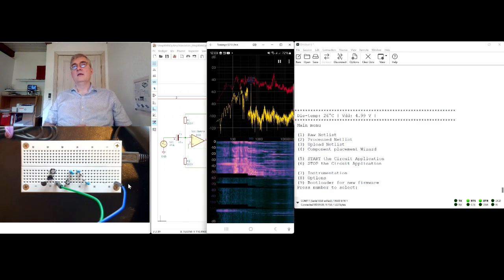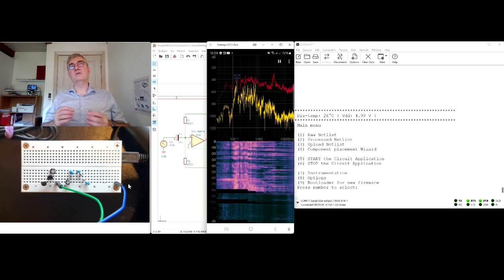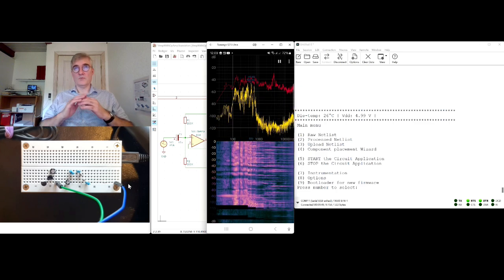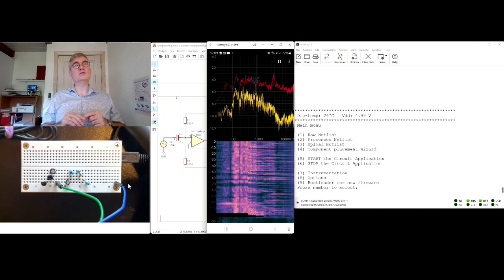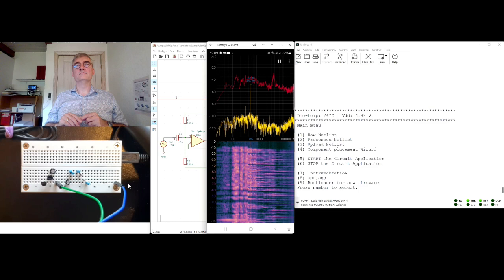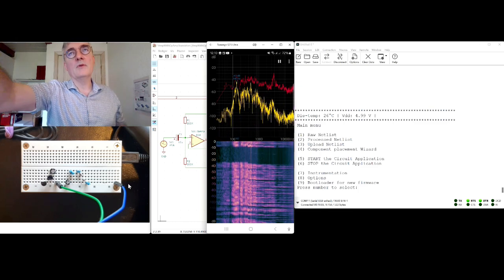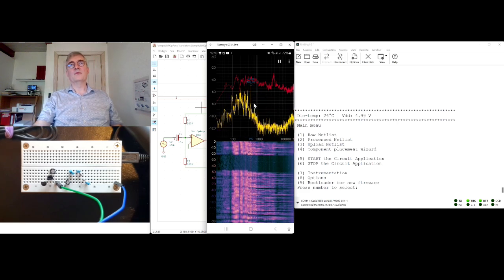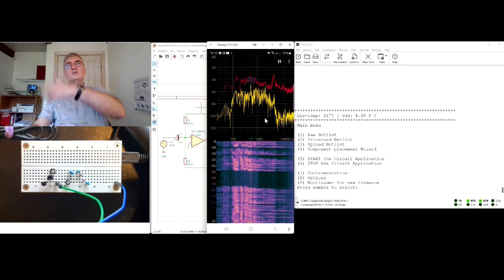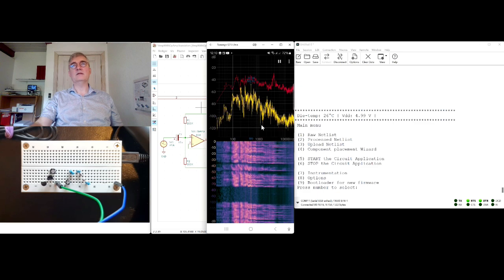There we go. This is just an application that I have on my phone where I can do a fast Fourier transformation of the sound in the room, and if I acquire it, you will actually be able to see that we have a tone there that is pretty much 500. There you go. And also what we call harmonics, those higher tones, you can see they are quite low, so we have a quite good sine wave coming out here.